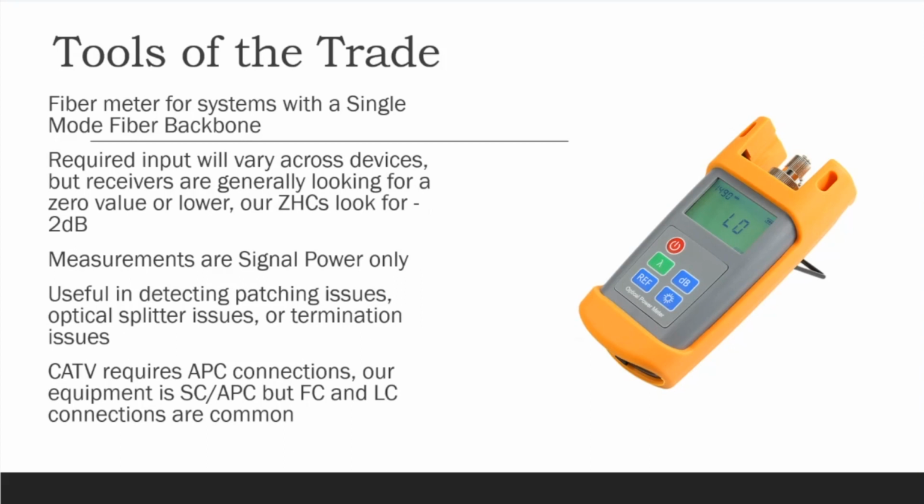The RF meter, the Televes H30 or whatever RF meter that you have and utilize, is the only place that we're really measuring quality. When we come back to the fiber meter, we're back to power. We don't have any way to measure quality again. This fiber meter is looking for either 1310 or 1550 nanometers. We're simply measuring the power of the optical feed